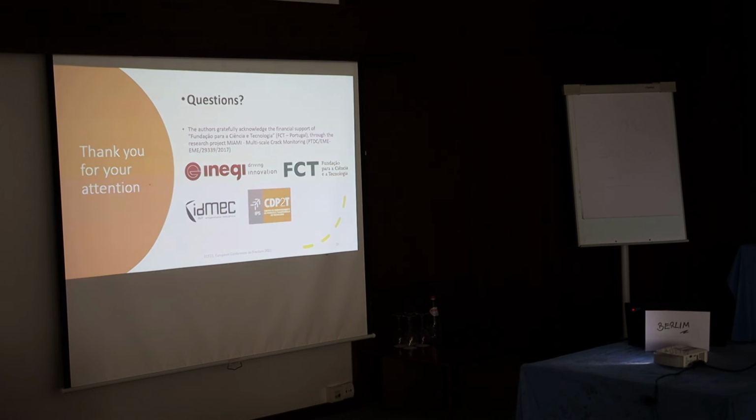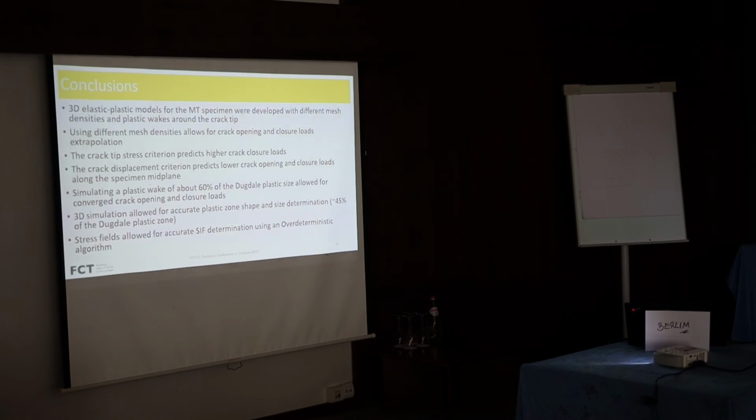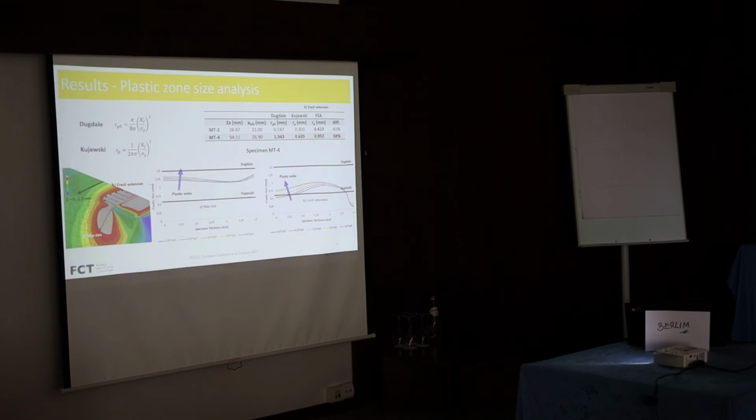Okay, and the plastic zones, can you show the slides with the comparison with Dugdale and Kujawski? One is the left graph and the right graph. It's at the beginning and at the end of the simulation. Yeah. And so the plastic zone is getting smaller because of crack closure.